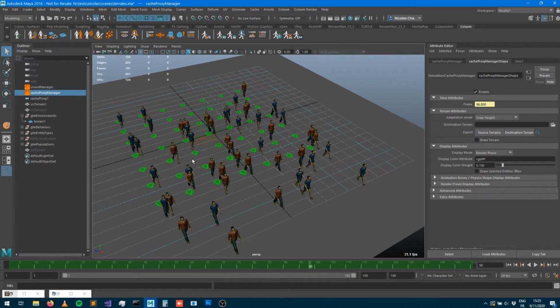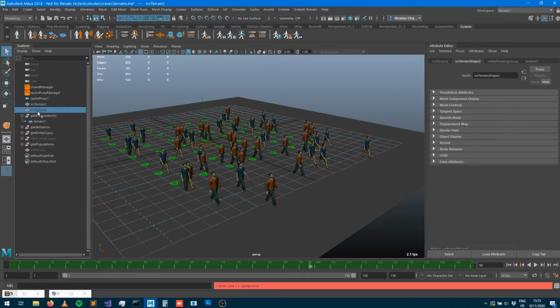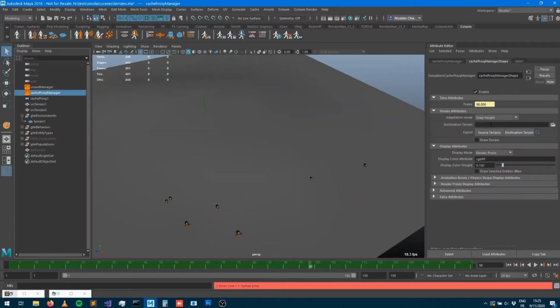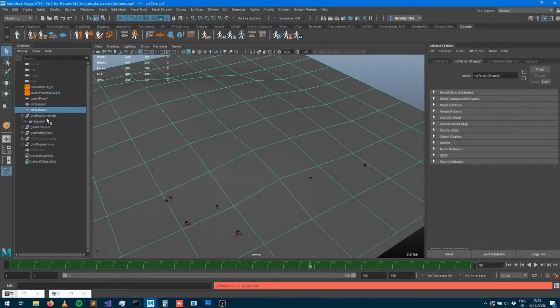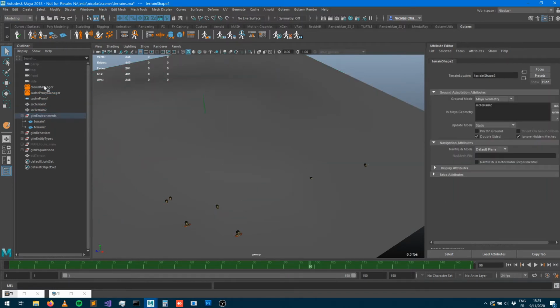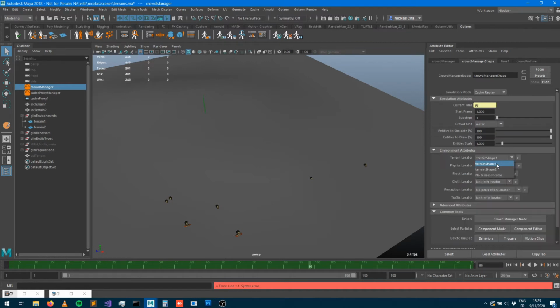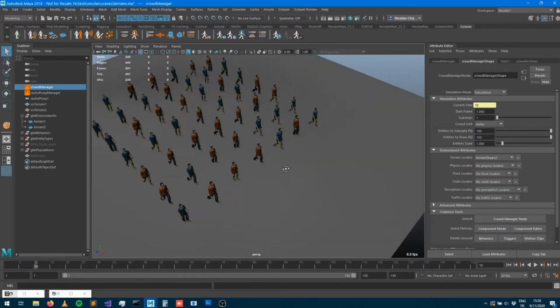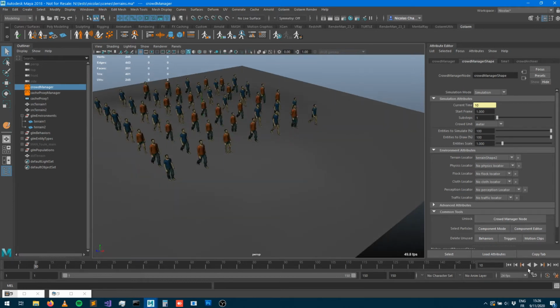Great. So let's say for some reason the simulation terrain changed, and now this is your simulation terrain. So sure, your simulation cache is not in sync with that. You can either decide to use that source terrain as a destination terrain at layout step, which means that now your characters in layout will be adapted to that new terrain. That's one option. But you can also maybe create another terrain from that geo, assign that new terrain to your simulation, and the next time you run the sim and export the sim, the characters will adapt to that new geometry terrain. So okay, great, that's exactly what's expected.